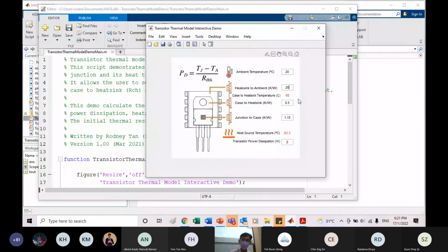So this is heat transfer. Switching losses lead to heat, and then what type of heat sink you need to use. This is another very common problem UCSI students always make. In your assignment, you all never put a heat sink. Because you're on for a while and off, no problem, right? Again, you are killing the transistor slowly.